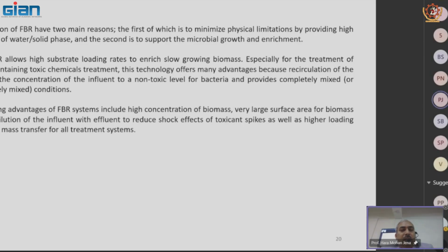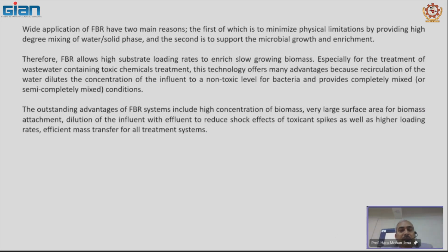The outstanding advantages of fluidized bed reactor systems include high concentration of biomass, very large surface area for biomass attachment, dilution of the influent with the effluent to reduce the shock effect of toxicant spikes, as well as higher loading rates and efficient mass transfer for all treatment systems.